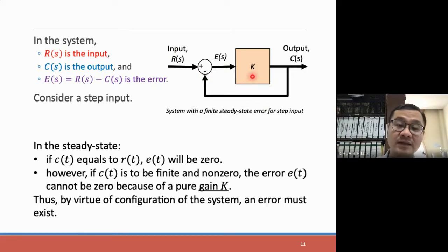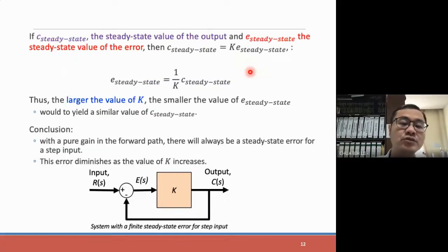But if the gain is, let's say, 0.8, then 1 multiplied by the transfer function gives 0.8. We compare it back, and the difference is 0.2. Then 0.2 multiplied by 0.8 gives 0.16, and so on. So it continues to loop. The error is mainly due to the setting of this gain value. So now, since we know that this gain or transfer function will play a role in determining the steady state error,